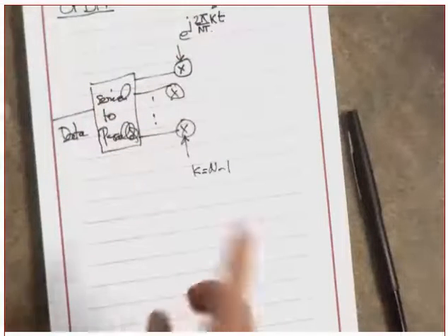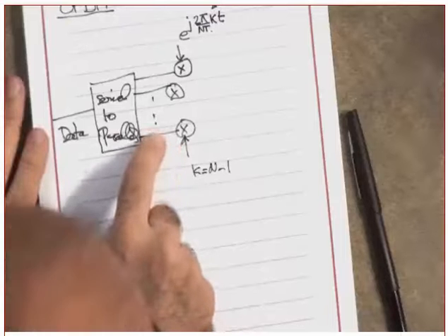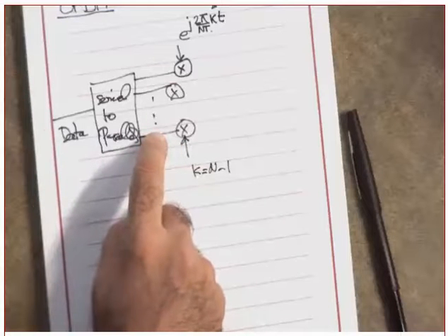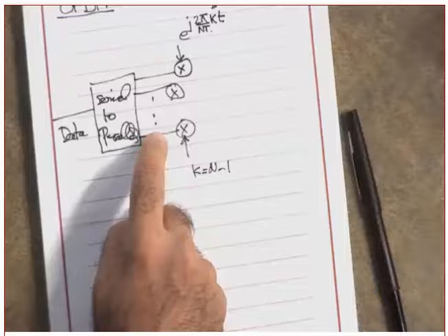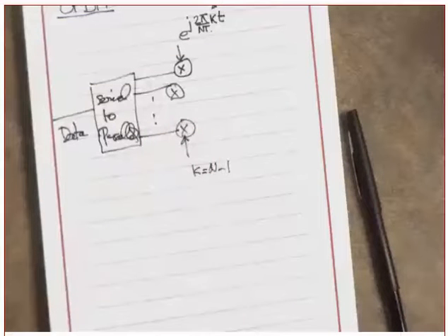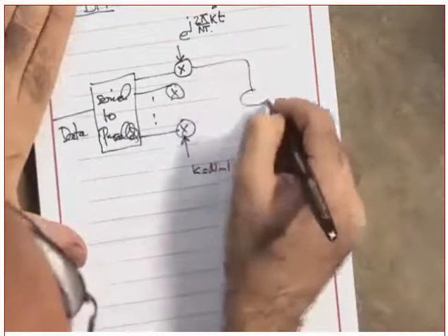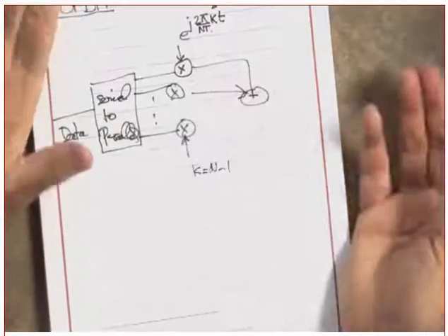In doing so, what did they do? They reduce the bit rate in here by a factor of N, which means to support this data stream you don't need a much wider bandwidth. Notice, by the way, they are going to add all of these things. Are you following me or not?